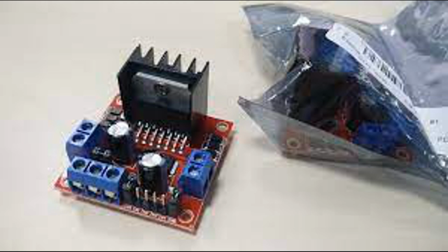Conclusion. Variable frequency drives, VFDs, are an essential component in modern motor control systems. By adjusting the frequency and voltage supplied to the motor, VFDs offer precise speed and torque control, improve energy efficiency, and extend the life of both the motor and mechanical components. They are used across a wide range of industries and applications, including HVAC, industrial automation, electric vehicles, and robotics. The choice of control method, whether V/F, vector control, or direct torque control, depends on the specific requirements for performance, efficiency, and precision in the given application.